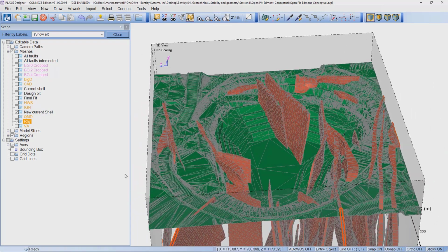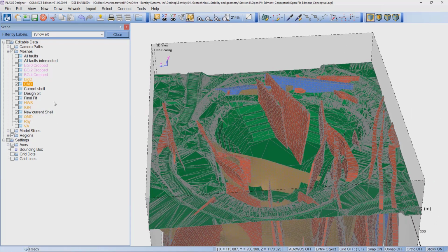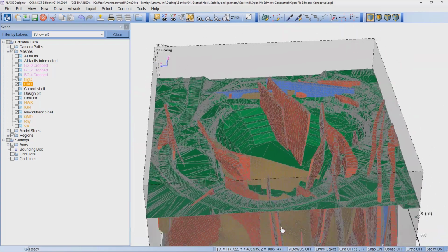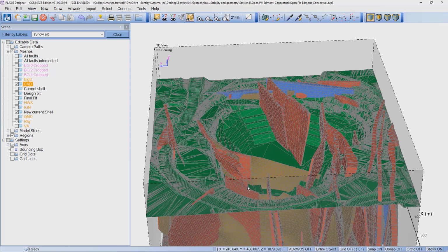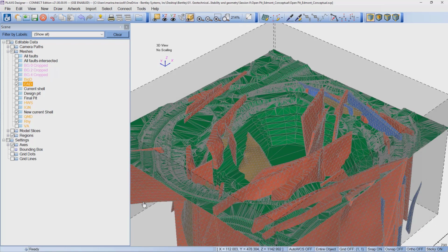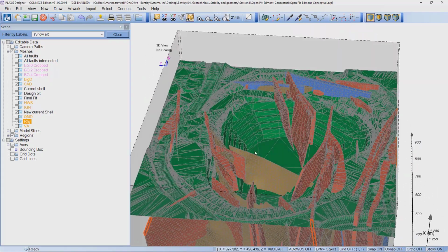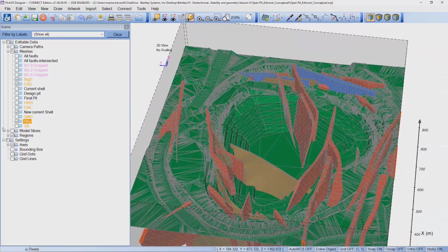We see that these volume meshes were imported from geological modeling tools that are extremely used for mining operations, and we can also use these volume meshes for our own benefit in the modeling. In this case, you see that I can import the volume mesh. I can use the volume meshes in PLAXIS 3D Designer. I could also build the volume meshes inside PLAXIS Designer if I want, by merging several meshes. And I can also make some adjustments to the meshes I have available here.